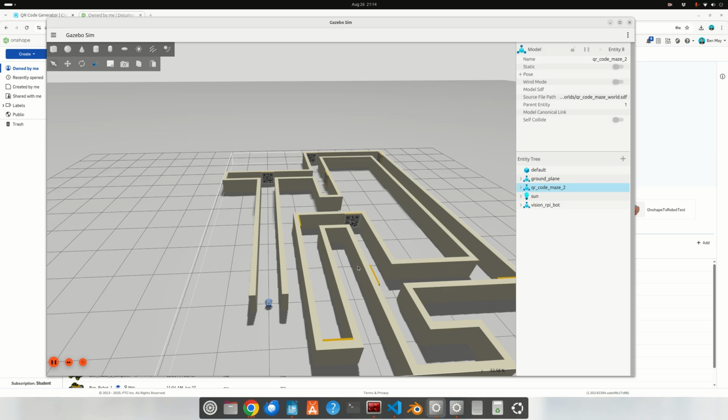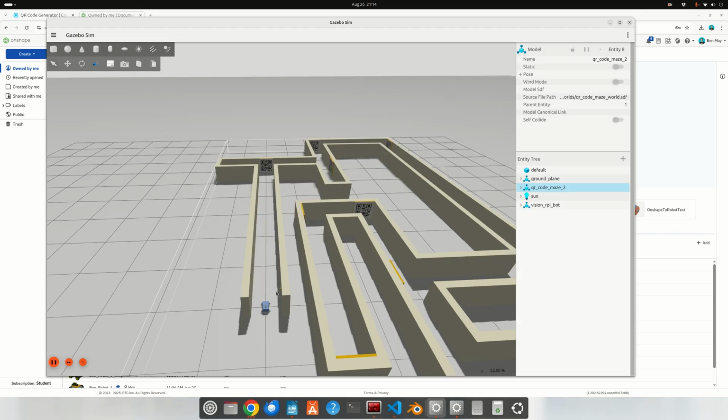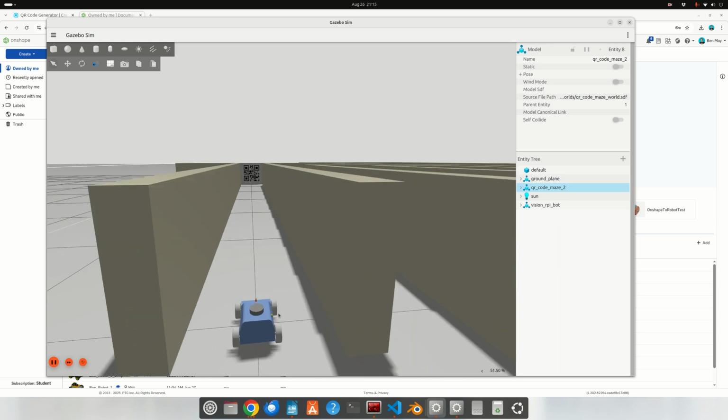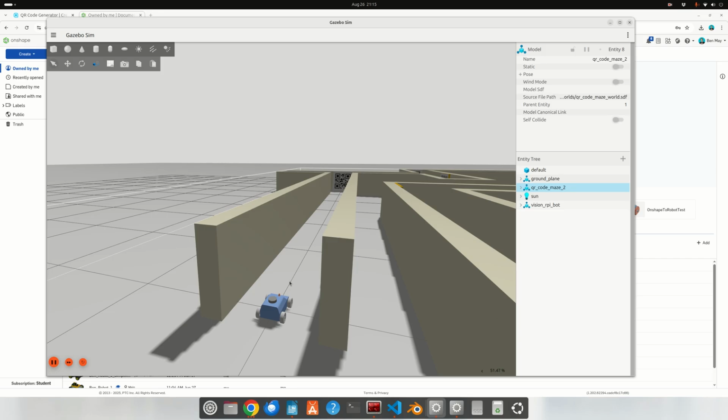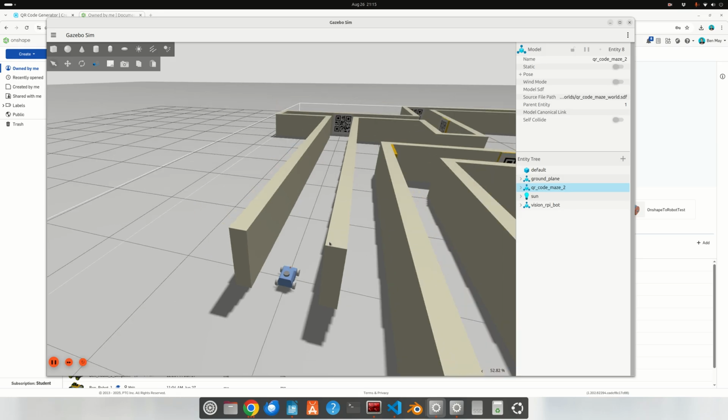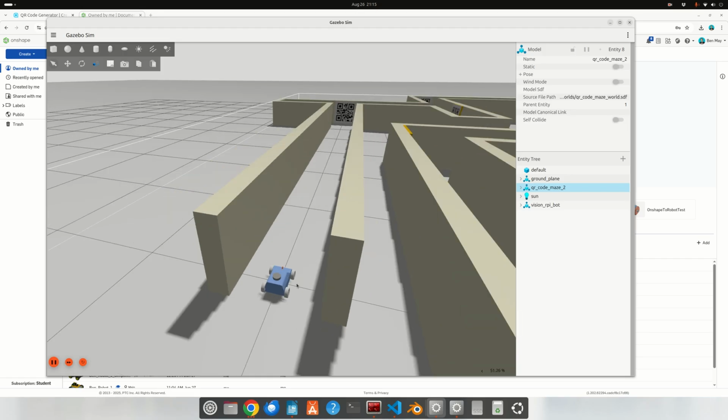Three, and probably the main reason I use OnShape, is the OnShape to robot feature. What that basically allows you to do is design a robot in CAD, export it into a URDF file, which you can drop straight into your ROS package, and you can then make some tweaks to make it Xacro and add Gazebo plugins. Now I'm not going to go into any of that in this video because it's a complete topic in itself. I'll show my entire workflow there in a separate video in due course.